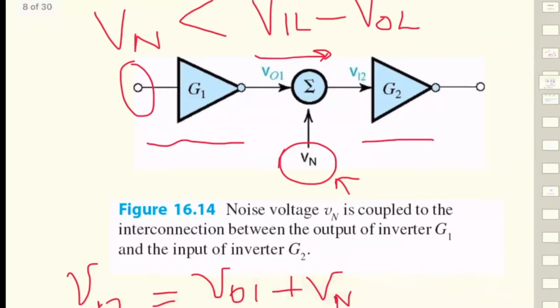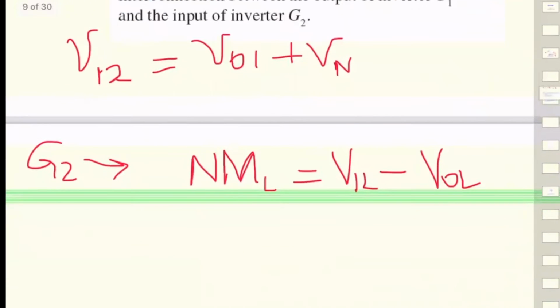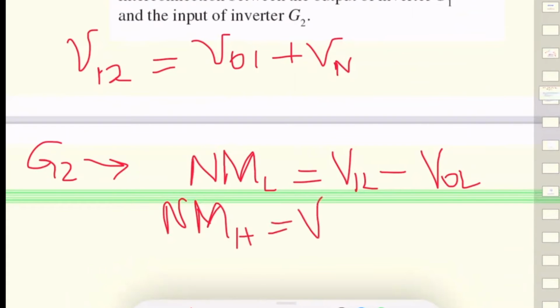So now, which means that I can set a higher noise margin as well, depending again on the VTC, which would then be VOH minus VIH. So these four parameters are important. Now we think about the voltage transfer characteristics. These four parameters are important for us to know, because that will tell us how robust our inverter would be.